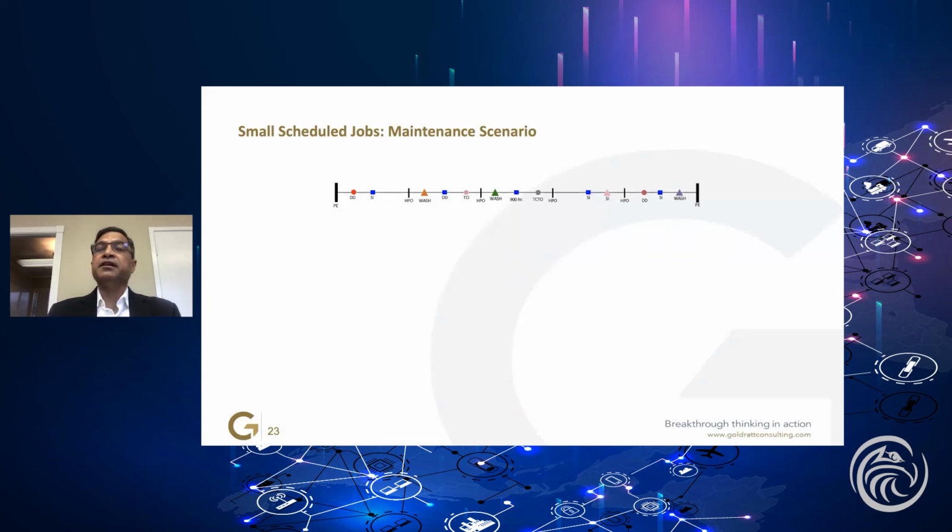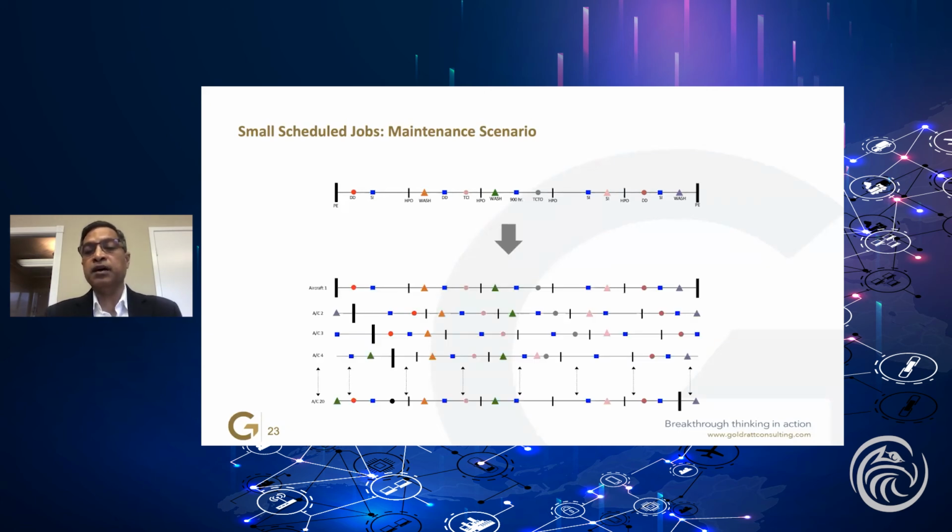And what we typically do in the traditional maintenance world is we try not to do the scheduled inspections ahead of time. So we would wait until as close as possible to when it's due, and then we would do the scheduled inspection, because the thinking is if I do it sooner, I'll do a lot more maintenance. But when I translate this idea into multiple aircraft, let's say in this example you have 20 such aircraft, and things are lining up this way.